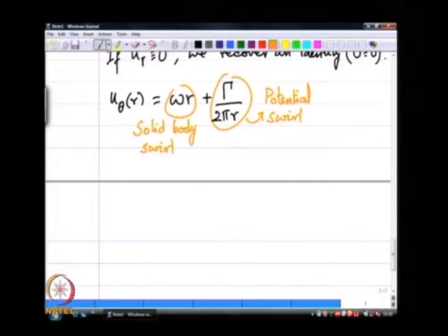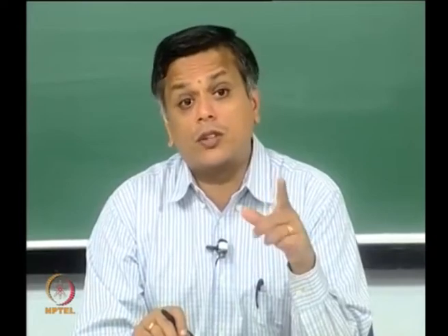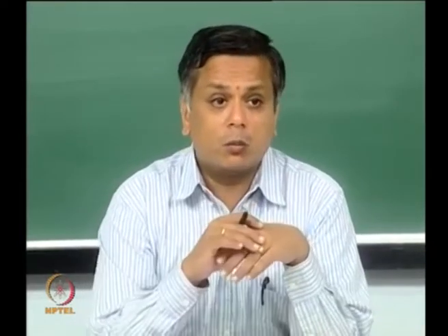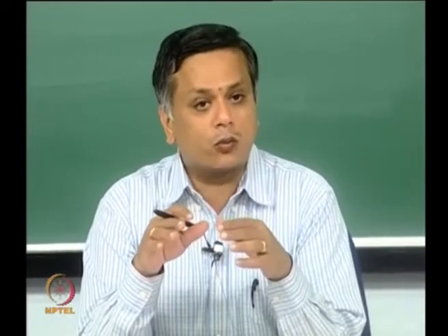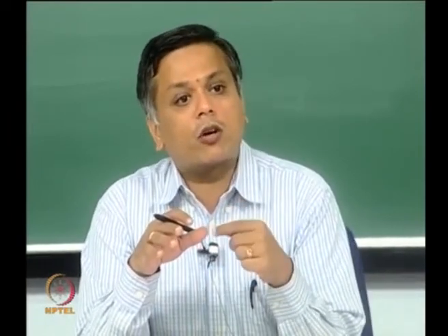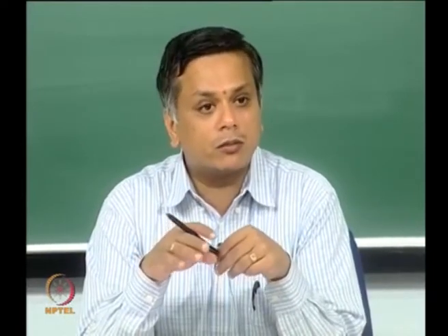So, if you look at any kind of a swirling flow, remember that we are not restricted to one of these two forms, except in the case of a viscous flow. We will look at that later on, but as far as inviscid theory is concerned, the only thing that you are allowed to conclude is that if you tell me what V theta as a function of r is, there is a corresponding pressure field associated with that, that can be calculated from the radial momentum equation.